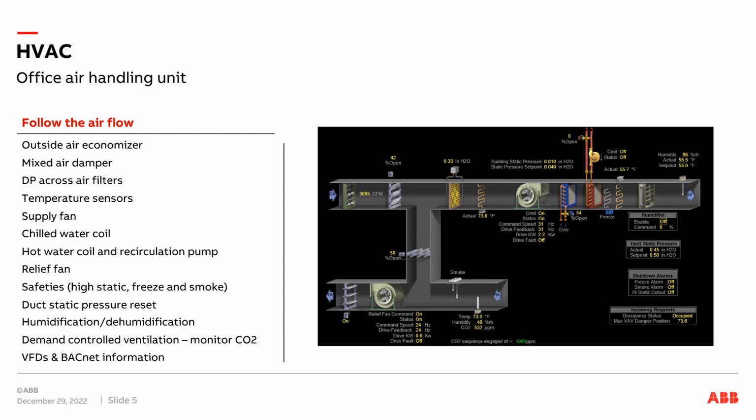So initially, high level, you're going to have outside air come into the air handler. It gets mixed with some return air. We'll get into those details in a little bit. There's some filters in there. Make sure there's no leaves or anything coming from outside coming in. There's a fan that blows the air. And then there's going to be some coils that either heat up or cool down that air based on what's going on.